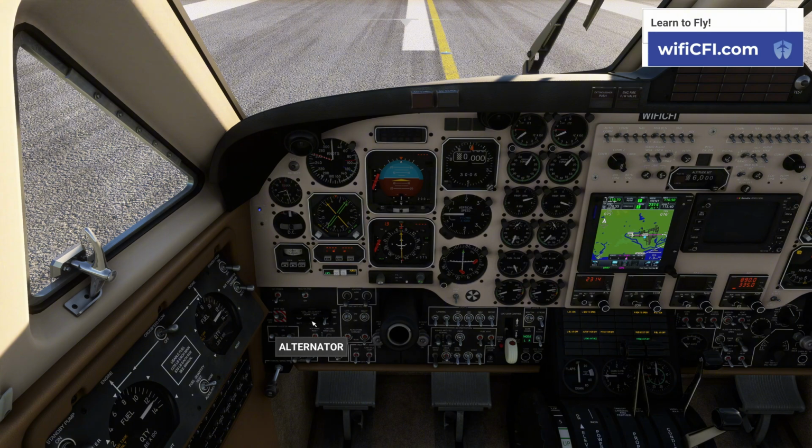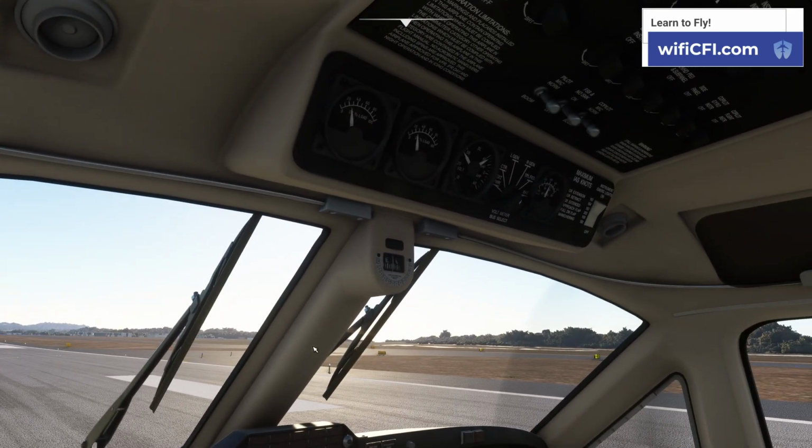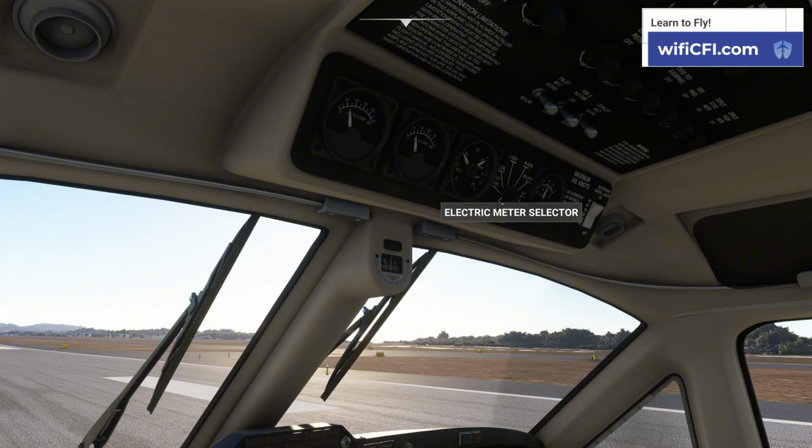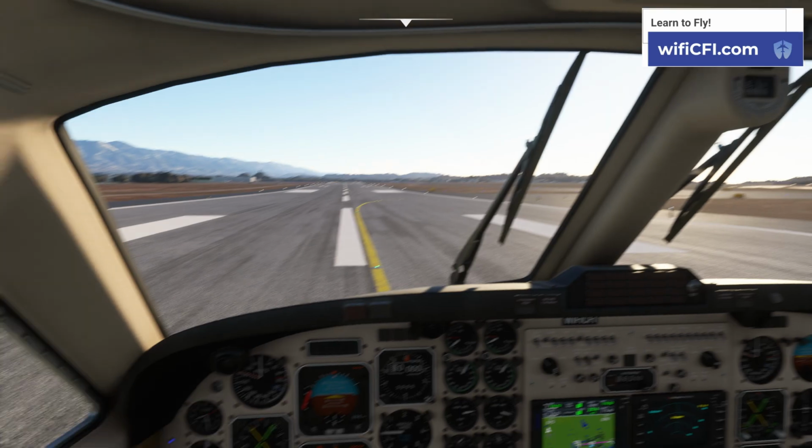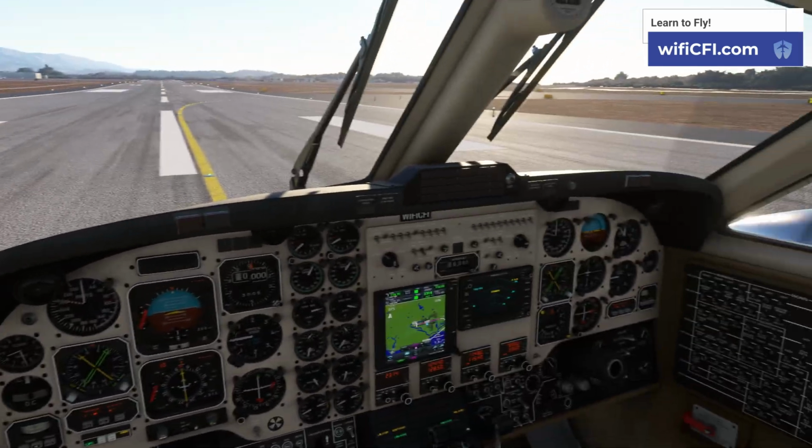And let's go and get our generators off. Here's our left one, our right one. Come up here, just check our voltages. A triple fed bus, right, left gen, 28. All right, looks good. Engines are running.